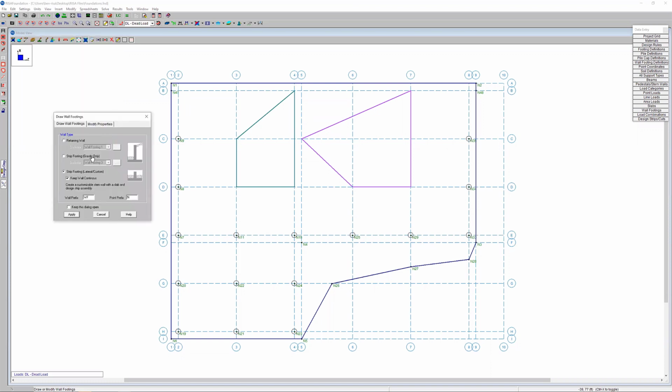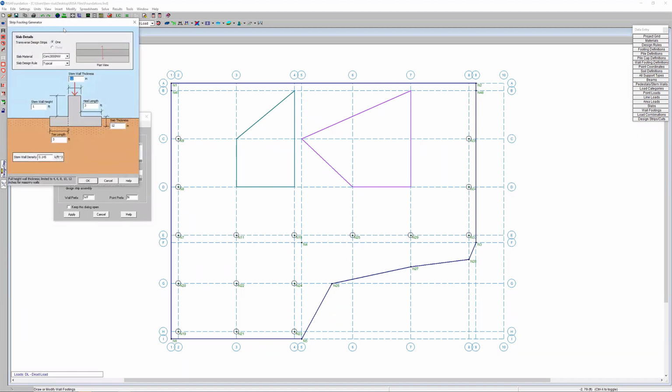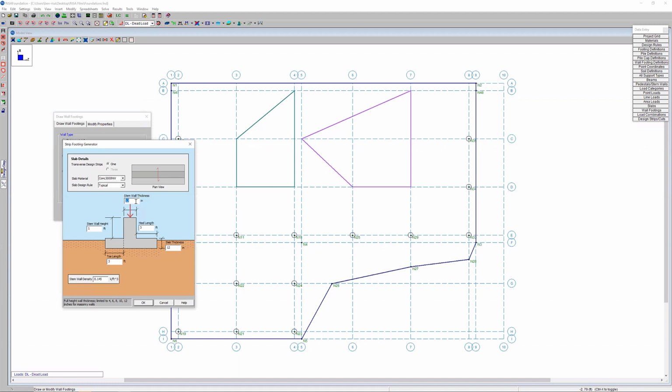In most cases, people are using these when they want to do a lateral wall footing, which basically amounts to a slab with a stem wall on it, or they have some other goofy condition in which a standard retaining wall or a standard strip footing isn't going to work for them. If I choose this, but then I choose to keep this wall continuous, I can set my criteria for this wall. So I'll set my stem wall thickness and my footing width.